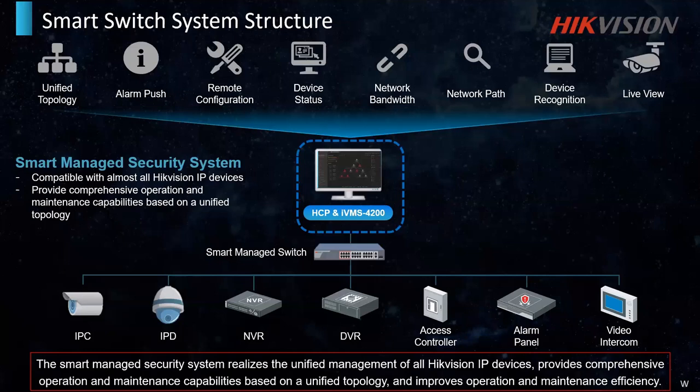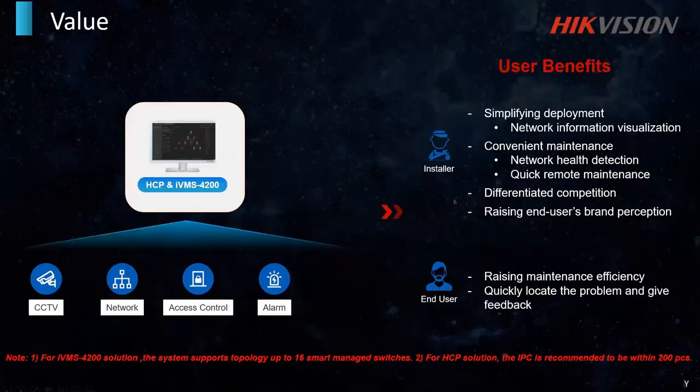I think the major benefit is using a smart managed switch, which is a small addition to the cost you pay for an unmanaged switch. I think it adds more benefit and is more useful when you are deploying your systems in this way. And we have some slides to show that as well, right, Varuna? So basically, the deployment can be very simple with this kind of a smart managed switch, and having a view of network health and remote maintenance is a very critical thing that you can use to easily troubleshoot.